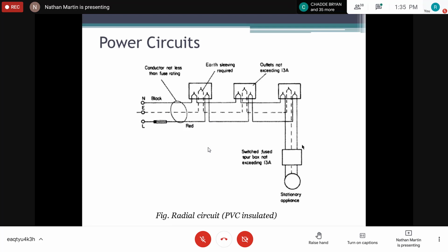However, most installations would be wired like this, rather than having a ring connection. The thing with the ring connection, we are talking about more conduits to feed a particular circuit, because both ends of the circuit must come back to your panel boxes, right?